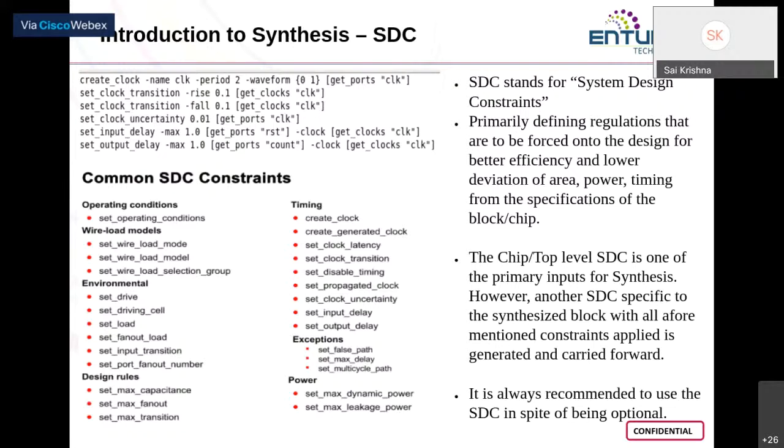It is the designer's job to understand the design, to understand its specification, and accordingly bring out the SDC. So SDC is basically optional. Synthesis runs even without an SDC with some default values, but it is very strongly recommended to frame a file for whichever design you use. The only thing is, if your design involves a sequential cell, if it involves a clock, you can name it. Else, if it is a purely combinational design, then maybe you can exclude all the constraints related to a clock, and stick to only your design rules, power, wire load models, environment, or operating condition.